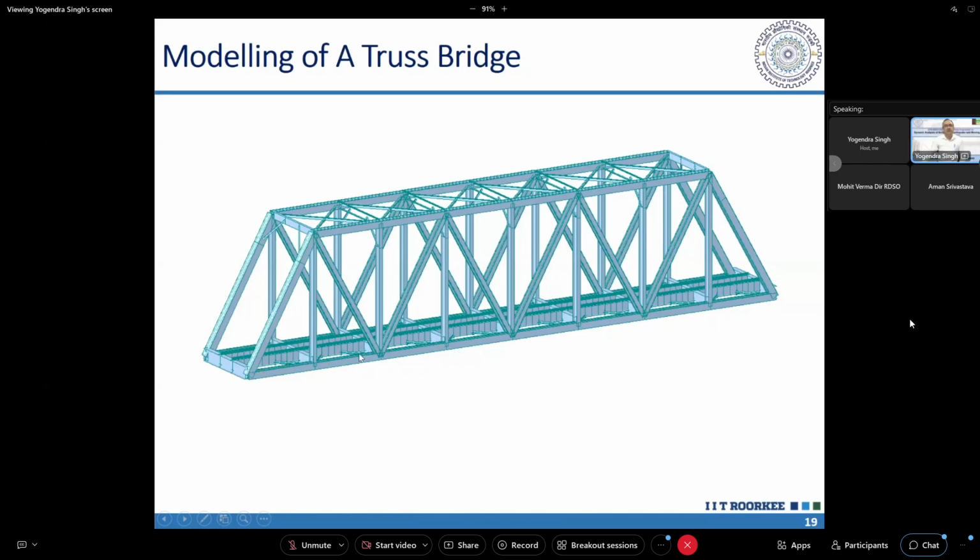So to the truss element, the load is being transferred at the nodes only, as is the condition in the behavior of trusses. And the bending is taken care of by these stringers. So these stringers are modeled as beams, and because our train will move on these stringers, the stringers have also been finely meshed. So you can see that the mesh is quite fine. Small beam elements have been used here, so that the wheel movement when it is taking place on the stringer can be captured correctly. The load can be transferred through these adjacent nodes.